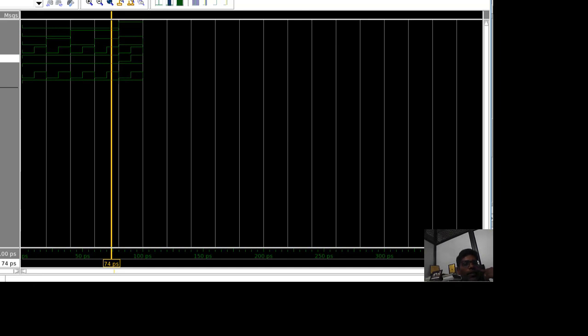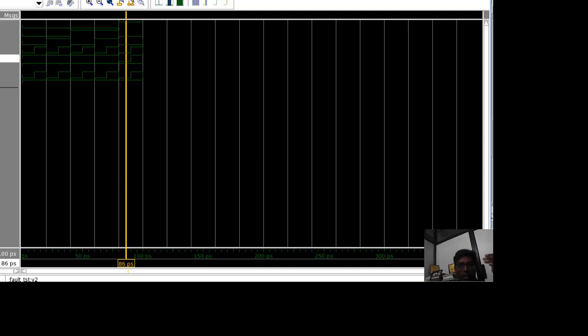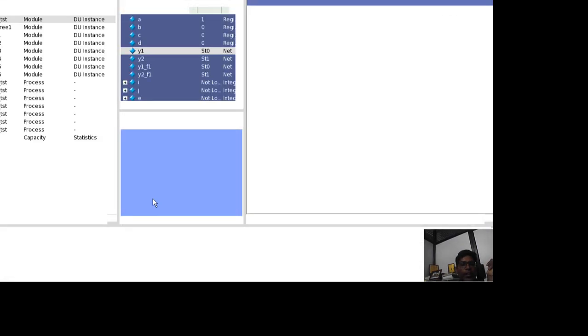So this particular test vector is not detecting any fault. Similarly, the vector 1000 gives me the same result as the faulty one. I have considered only one faulty circuit. Like this you may have 6 faulty circuits in the network. So you are expected to go with all 6 and see, for this particular test vector, which faults have been captured. I believe you got it.